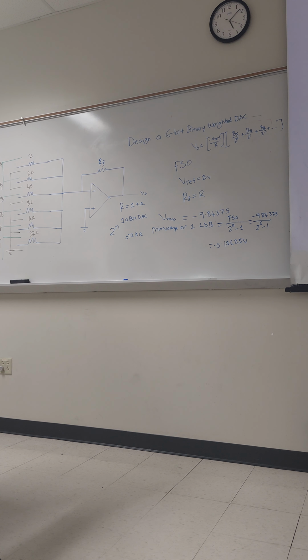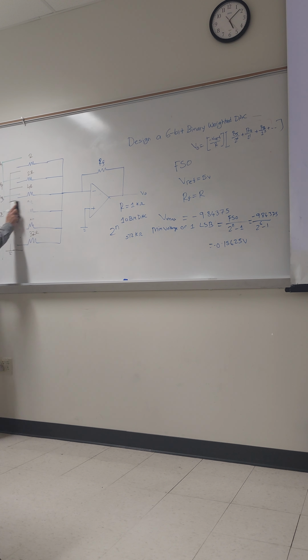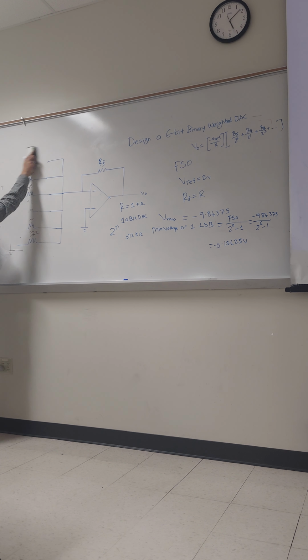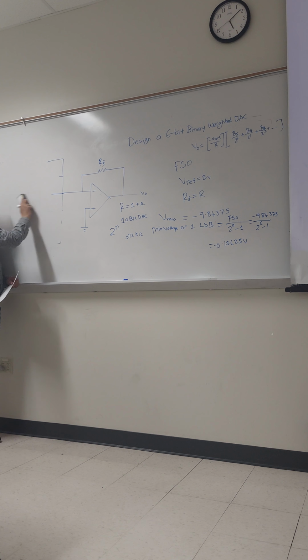It is also known as a resistive ladder circuit. Here the problem is we need very precise values of resistors, so many resistors. If you keep increasing your number of bits, you need higher values of resistors, and they should be in the power of 2.